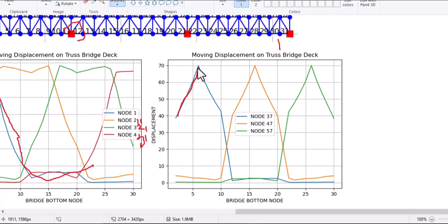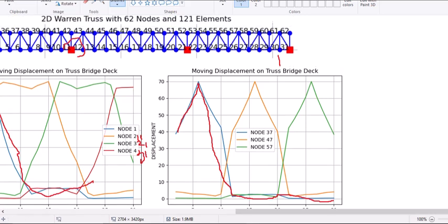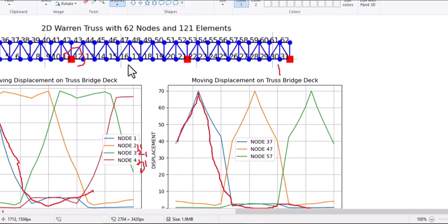So in here we have very critical conditions, and then the structural displacements go down. Then in here we have a very smooth line, and then it's going to be 0. And also you see that, guys, if we increase the displacement in the pushover analysis in here, for example, at the bottom or top, it has this shape.